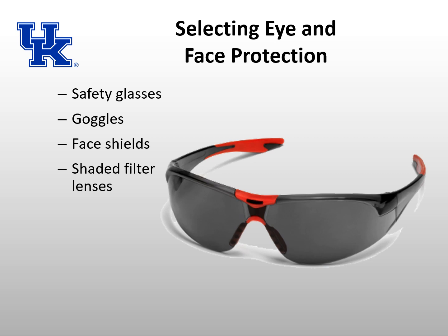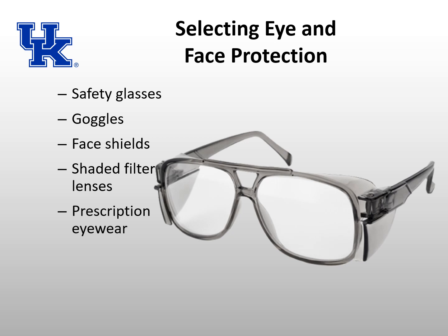Shaded filtered lenses are worn to protect against potentially harmful light radiation, such as from welding operations or certain laser equipment. Prescription safety glasses may be appropriate if you need corrective eyewear. Wearing contact lenses is not recommended when exposed to such a hazard as dust, hazardous liquids, or vapors in high temperatures.